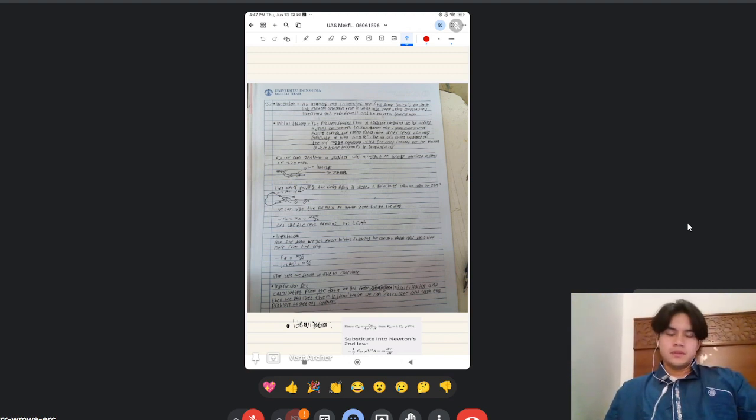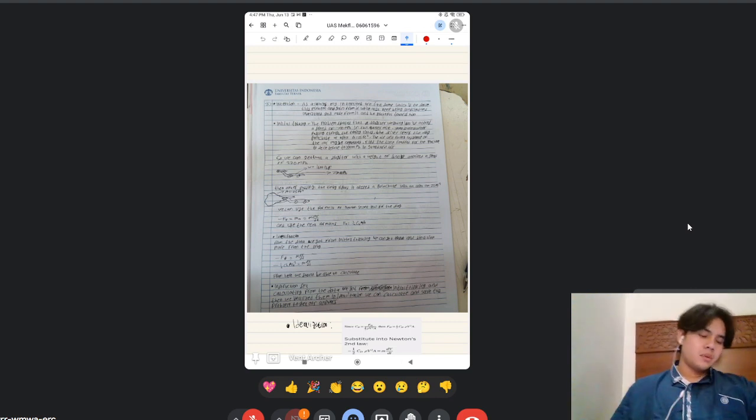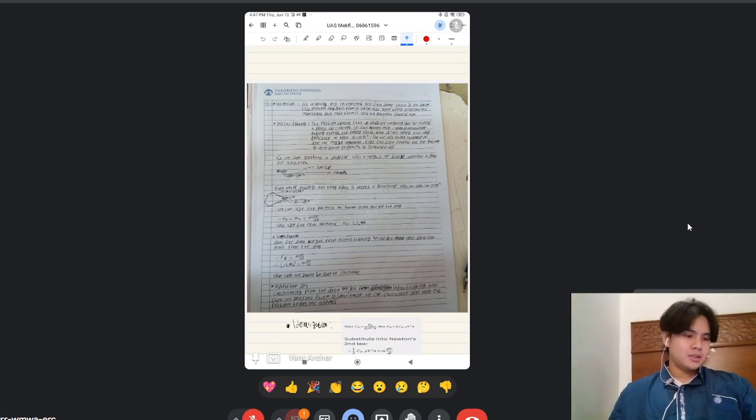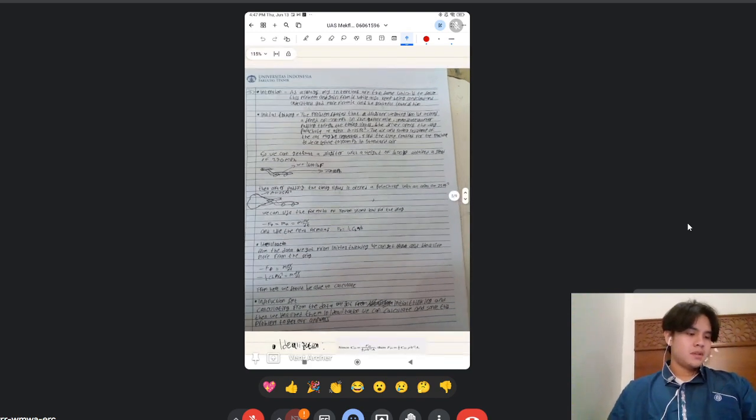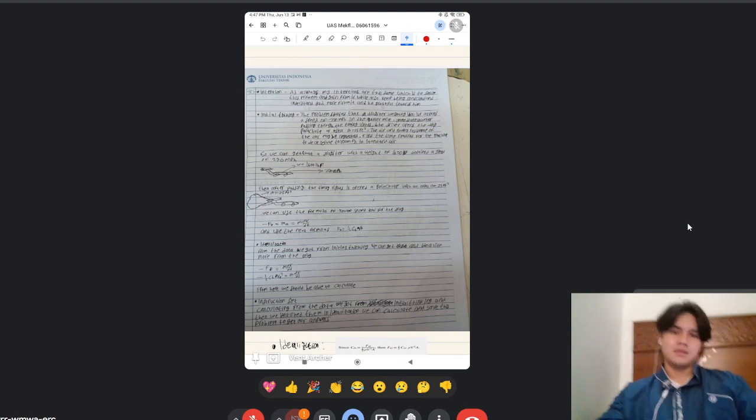And moving to the initial thinking for problem number 3. The problem states that a dragster weighing 1,600 pound force attains a speed of 270 miles per hour in the quarter mile immediately after passing through the timing lights. The driver opens the drag parachute of area 25 feet squared. The air and rolling resistance of the car may be neglected. Find the time required for the machine to decelerate to 100 miles per hour in standard air.